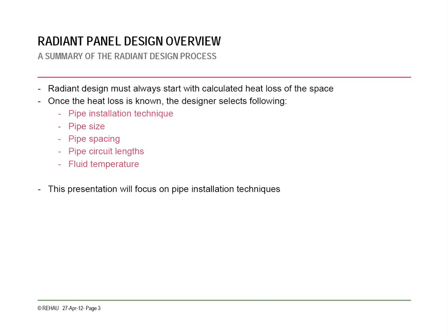You always want to start your design knowing what the space is going to be used for and the heat loss associated with that space or the amount of heat you're putting into the space. If it's floor heating or floor warming in a bathroom, you're not necessarily working with the heat loss. You're working based on just warming the floor.